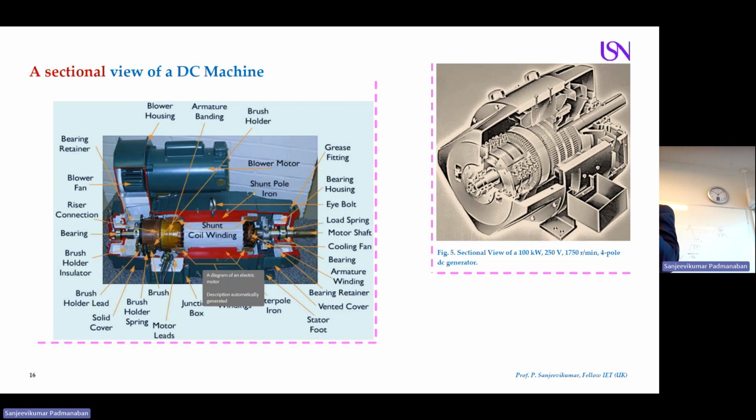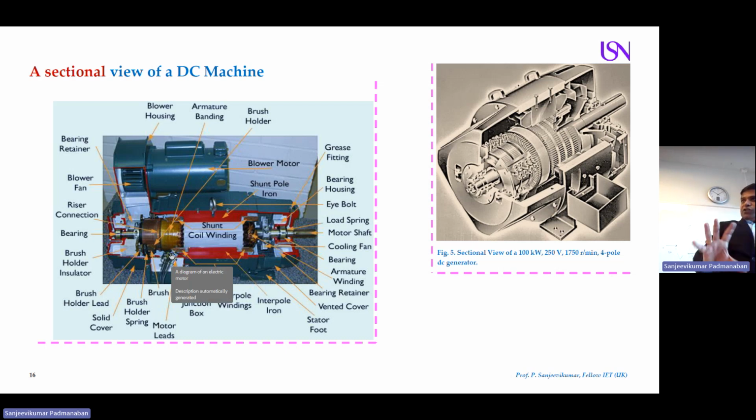How much heat can the machine produce? When heat is produced in your coil, the inductor will lose its property and weakening of inductance will be created, and the machine will deteriorate. I'm right. In order to avoid these problems, we are using blowers, which can blow air inside your machine, not for small machines, for big machines. You blow air and keep the coil poles cool. For this purpose, we are using blowers.